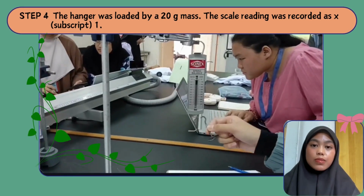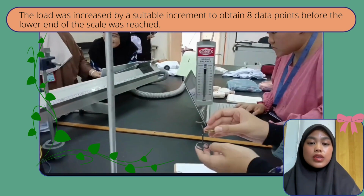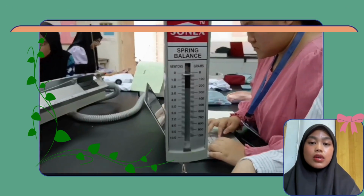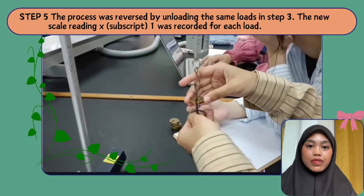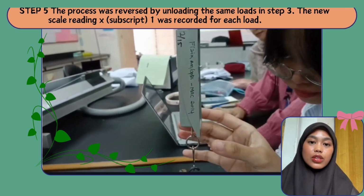The hanger was loaded by a 20-gram mass. The scale reading was recorded as x1. The load was increased by a suitable increment to obtain 8 data points before the lower end of the scale was reached. All data, W and x1, were recorded. The process was reversed by unloading each load in step 3. The new scale reading, x1, was recorded for each load.